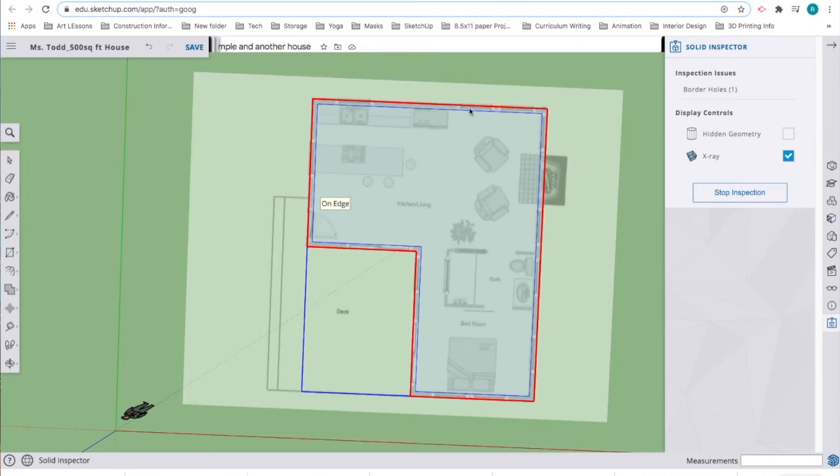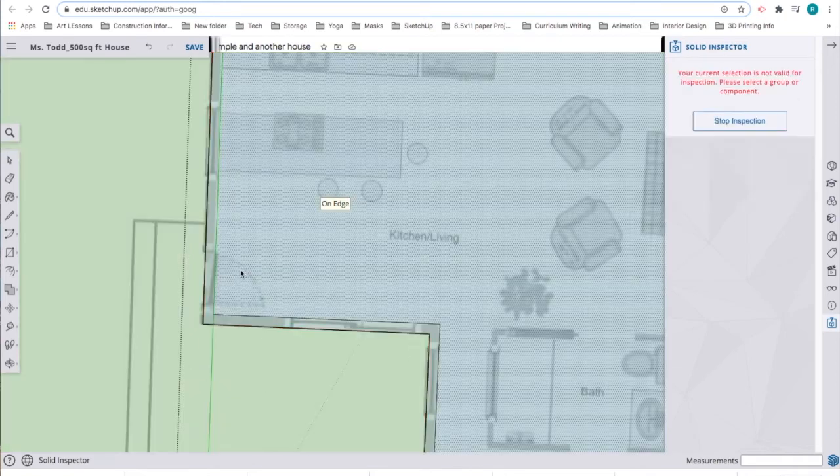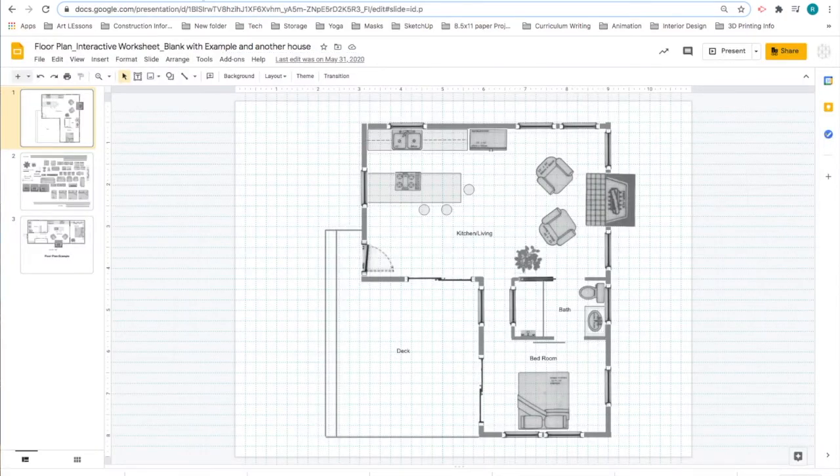This is going to be important because you need to know where you're going to place your windows and your doors. So I'm now going to go into edit mode. Remember that we have two: the walls that are the outer part, and the inside, which are the floors. What I need to know now is how wide my doors are. Hopefully, when you were creating your floor plan, you can come back and look to see how wide your windows were. In my case, a lot of these windows are all 3 feet. None of them are 4 feet. They're all 3 feet wide.